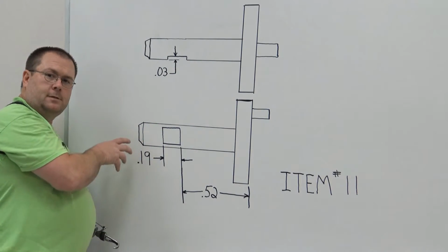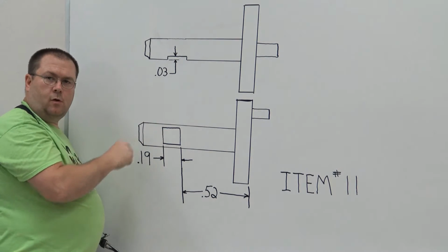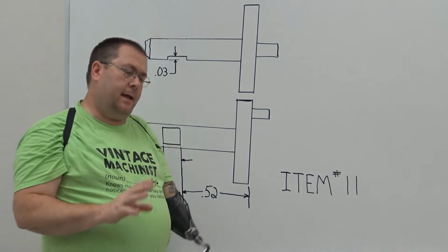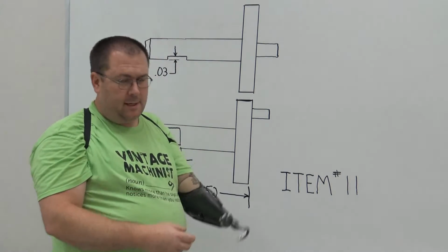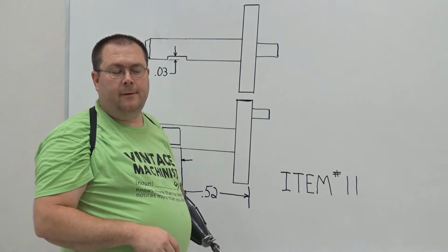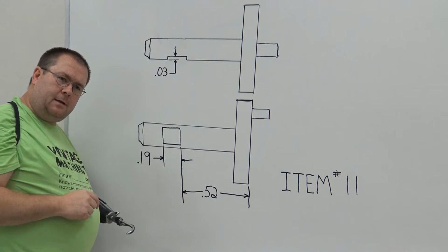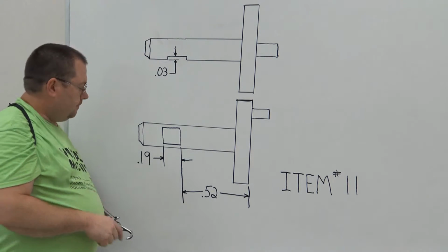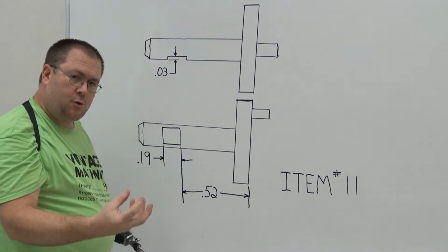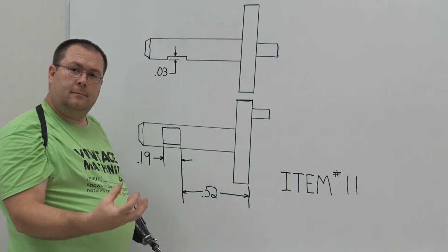Well, there's a different style collet that's mainly used on lathes, but we do use it to hold round stock in mills. It's called a 5C collet. Again, that's a standard that says a 5C collet is this diameter, this taper, this length, and has a thread on the end of it. What's important when I pick a size of a collet? That if I'm holding on to a 3/16 diameter, I have to make sure that I've got a 3/16 diameter collet, right?